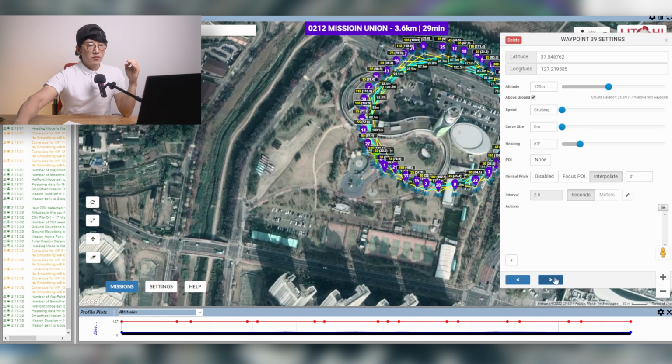At the end of the flight, I flew my drone up and manually captured the top of the building with a -90 degree gimbal pitch. So it captures like this, and a second photo like this, and again other angles. Let's capture 3 photos. I'll show the photos later.